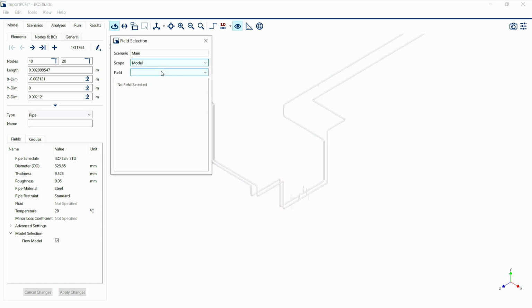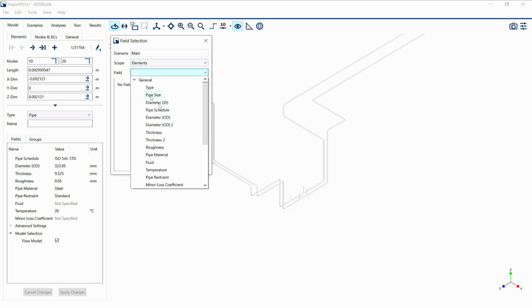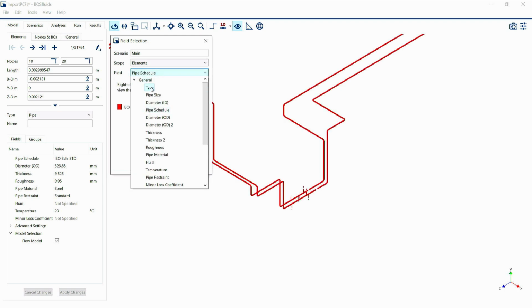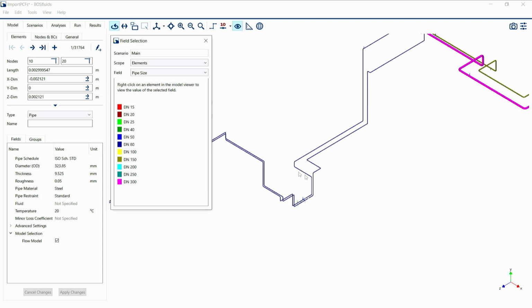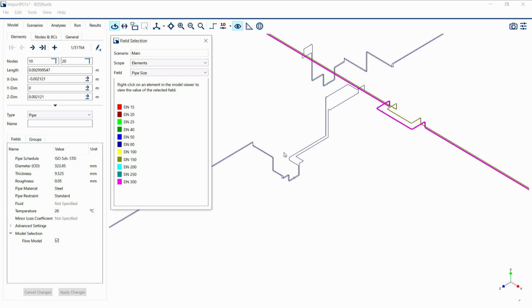And you see that now it makes use of the new pipe specs. So the schedules are recognized, all the pipe sizes, and this can greatly help you just also running your system on the 3D model instead of a schematic. It improves the accuracy of all your forces and the results, and makes it easier to communicate again back to the design team if there are any mitigations required for large forces, for example.